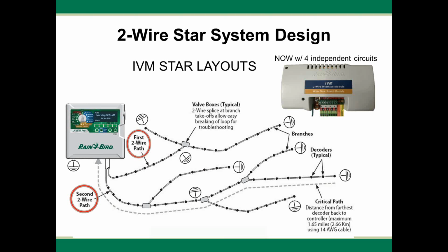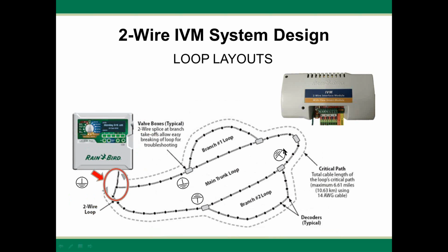I was just listening to and reading up on one of the other competitors, and controllers that cost twice as much as these, when they have a short, they stop irrigating the entire facility. So keep in mind, when we have a 4-circuit layout, we do want to make sure that we understand the differences in those circuits. Coming from distribution, I'm well aware that we don't want to carry more SKUs in distribution. However, it's highly advisable that when you do create these different circuits, use different colored wire for each circuit. That way, when you create a loop out in the field, you can create that loop and come back in with the same colored wires.